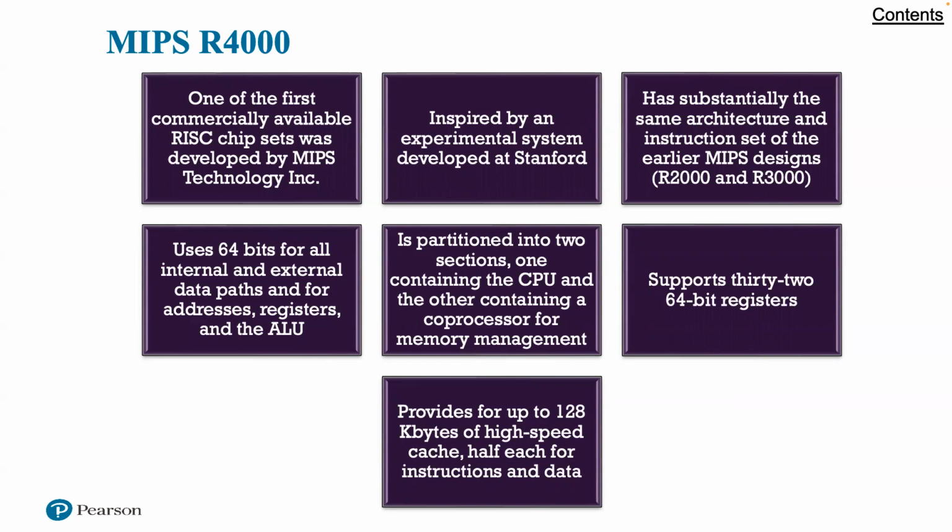The use of 64 bits has a number of advantages over a 32-bit architecture. It allows a bigger address space, large enough for an operating system to map more than a terabyte of files directly into virtual memory for easy access. With 1 terabyte and larger disk drives now common, the 4 gigabyte addressing space of a 32-bit machine becomes limiting. Also, the 64-bit capacity allows the R4000 to process data such as IEEE double precision floating point numbers and character strings up to 8 characters in a single action.